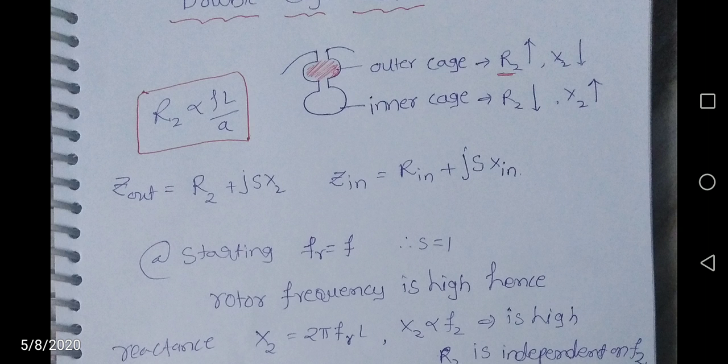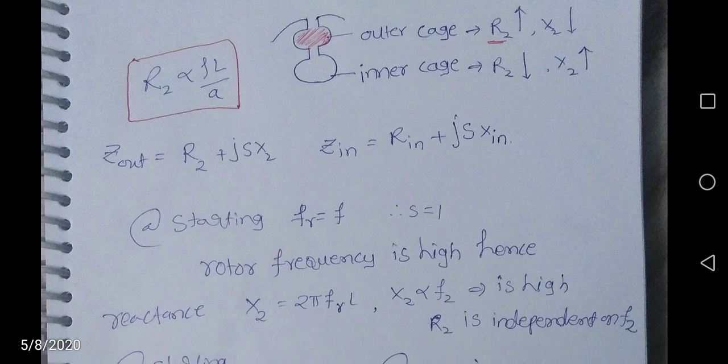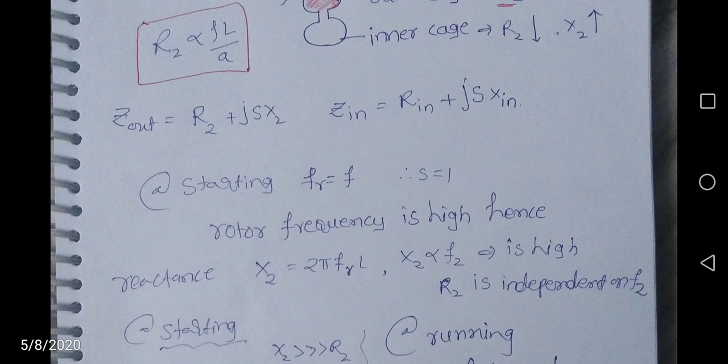At starting, rotor frequency is equal to stator frequency. It is because slip equals 1. Slip is 1 because NR equals 0; substituting NR equal to 0 in the slip formula, we get slip equal to 1.